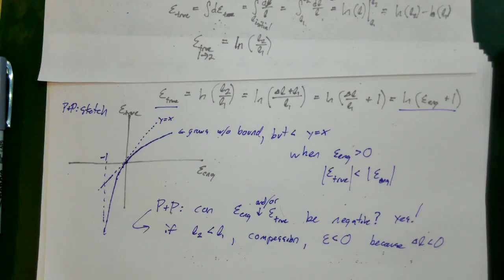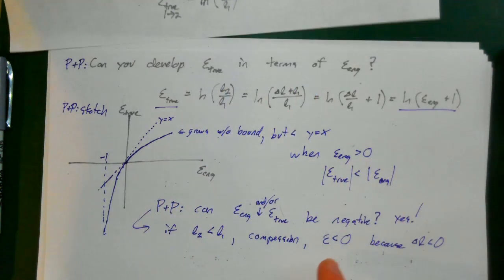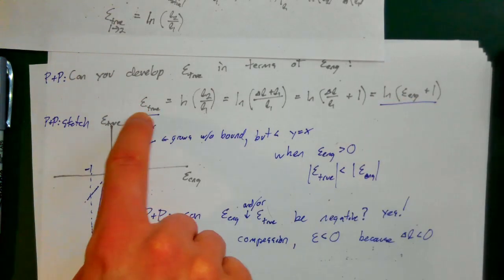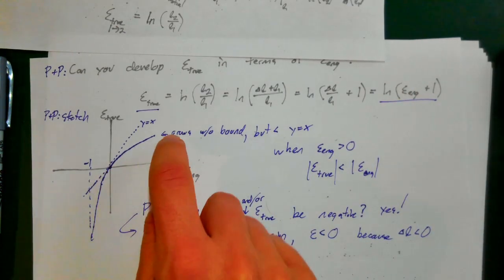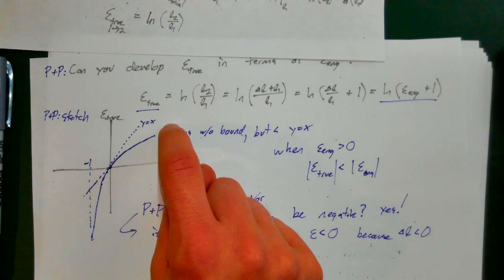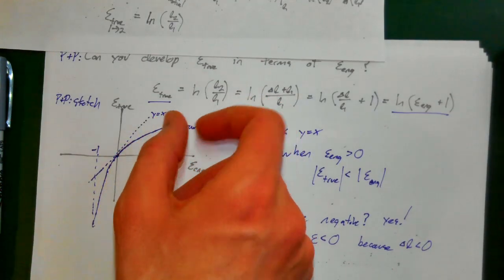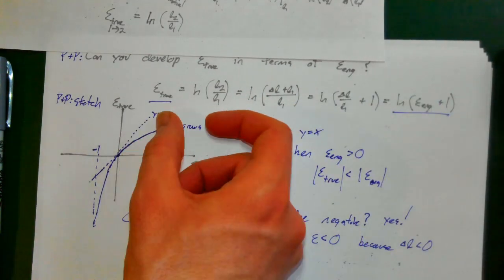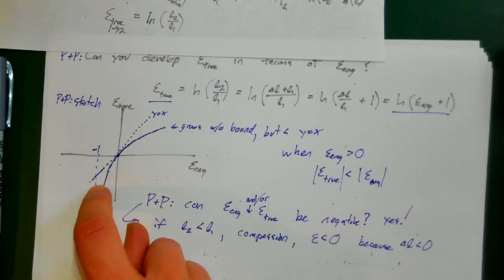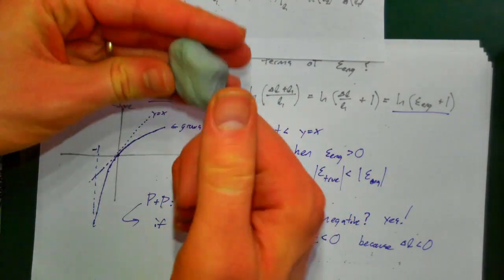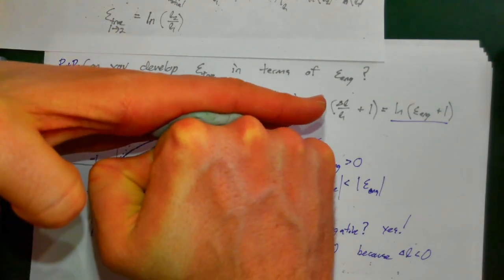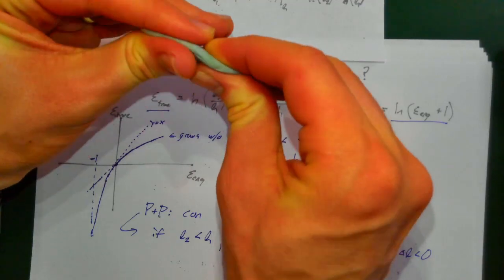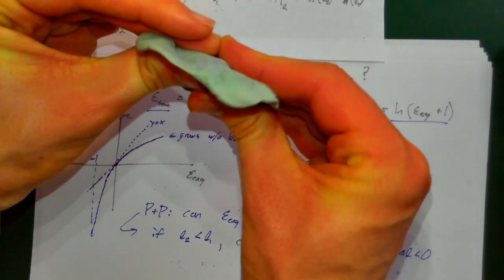But anyway, I digress. True strain is related to engineering strain by this relationship here. Basically what this is saying is, when you're stretching something out, once it's already stretched a lot, it doesn't really feel like it's getting stretched much more. And if you're compressing it, it actually starts to feel more and more of an intense strain phenomenon as you're squishing it down into a smaller and smaller pancake.